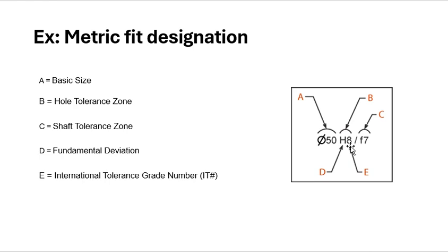8 is a tolerance. Go back to the table and you can read what that is. It comes from the table, how to read it, but you know that this is a whole tolerance zone, because it's in capital. The small case is your shift tolerance zone, C, so therefore that's your shift tolerance zone. Of course, they have their own magnitude, which you can go back to your table to look at, what they mean.